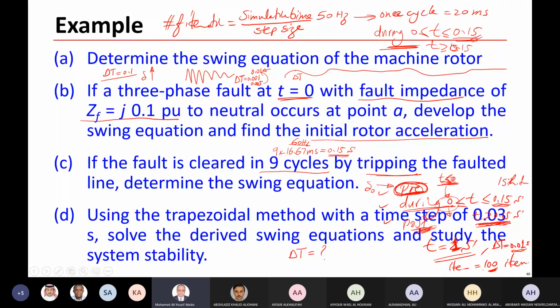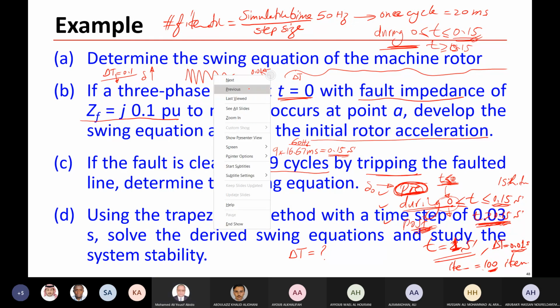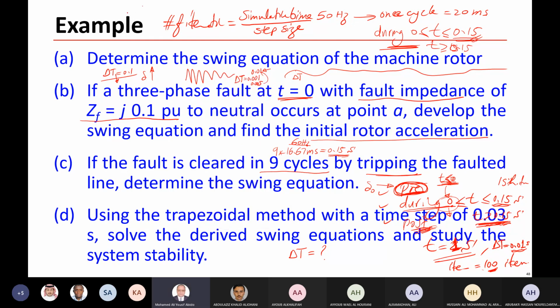In this case, you need to reduce this delta t, and carry out the simulation again and see. But if you start with a very small value, and you find out, this is delta versus t, you will see delta increasing monotonously as such. So in this case, the system is unstable. Okay.